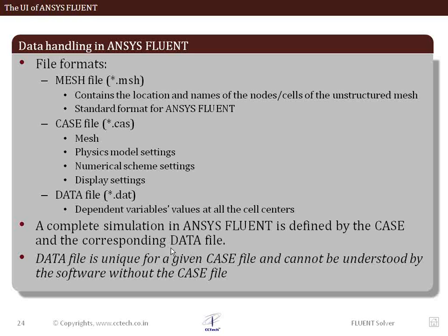Certain things need to be understood about the case and data files, especially that the complete simulation process along with the results is understood by ANSYS Fluent only when you read in the case and the data file. So let's say I do a simulation, I need to write the case and data file so that I can retrieve the data at a later stage. A data file on its own does not have any sense.